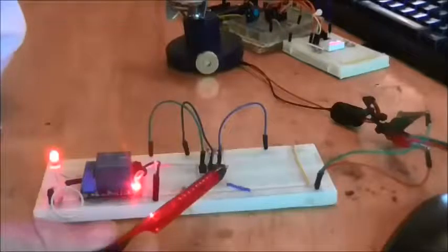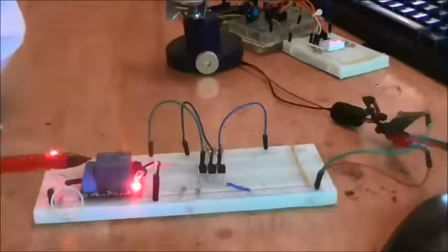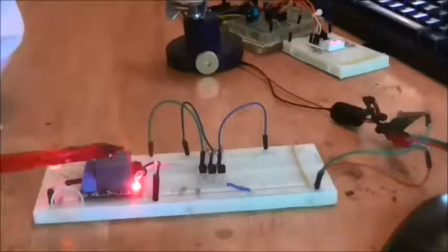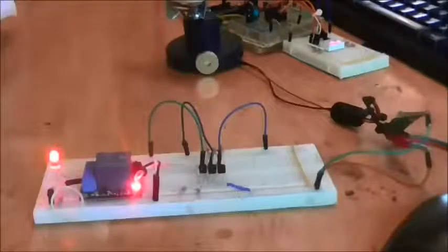Now, the logic gate is a 5 volt device and the siren can be 9 to 12. So, by using an electrically isolated system like this, I can accommodate those 2 voltages by putting in 9 volts and regulating down to 5. And if you watch the video on diodes, then you'll know I can do that with something like a Zener diode, or indeed I could use a standard chip regulator.